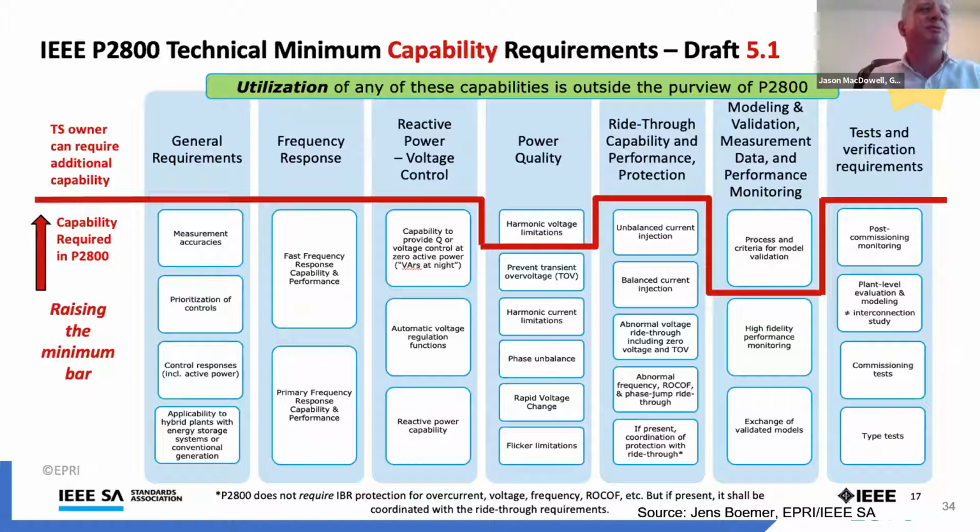and active power absorption during charging. So there's a bidirectional element now when we have batteries that are integrated in a hybrid mode with power plants or standalone to support grid needs. All of that is specified in the IEEE P2800 capability of the standard. And it's, again, a matter of taking those suggested minimum requirements and incorporating them into all of the regional interconnection requirements and national interconnection requirements going forward.